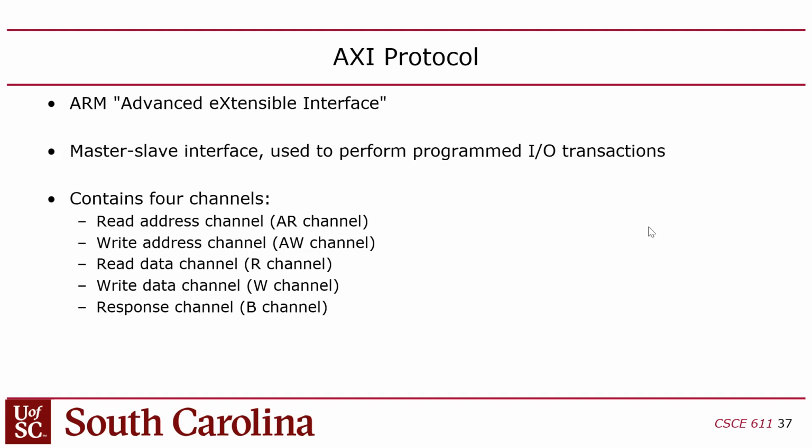But what about an example where you actually have to design a state machine controller? When would you have to do that? Well, that's whenever you have things going on at the time scales of the clock, right? Like single clock cycles, right? That's when the dynamics are too fast to use software, where you have to use a hardware controller, right? And I think one of the most common examples are bus protocols. So the most common one is AXI, which is the one that's in everyone's phones, basically. It controls basically all the consumer embedded systems.